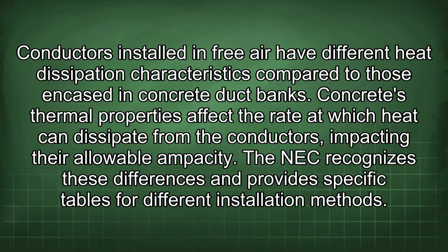Conductors installed in free air have different heat dissipation characteristics compared to those encased in concrete duct banks. Concrete's thermal properties affect the rate at which heat can dissipate from the conductors, impacting their allowable ampacity. The NEC recognizes these differences and provides specific tables for different installation methods.